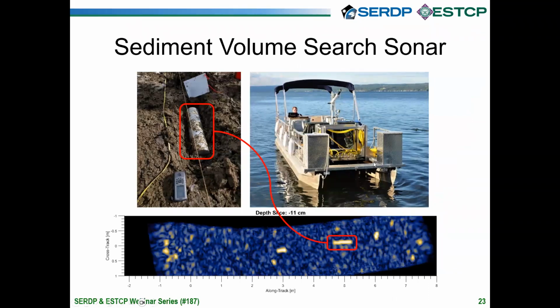So the actual sonar system itself is seen here in the forward portion of this pontoon boat. The sonar system is mounted to this black metal plate. You can see the cables and connectors carrying all the wires that attach to the hydrophones and the projectors on there. And so we transit out to some site where we want to conduct a survey, and we use this little crane arm here, and it lowers this plate into the water down beneath the pontoons, right? So we transit to the site with the array plate up, and then when we get to the site and we're ready to conduct the survey, we lower the sonar system into the water, and now we're configured into a mode where we're ready to conduct our acoustic survey.